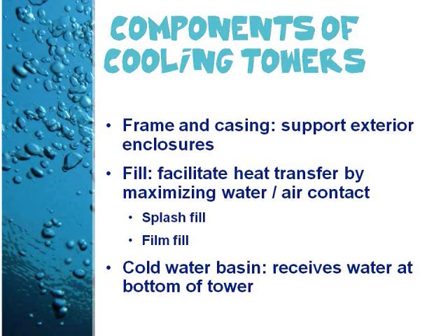The cold water basin is located at the bottom of the tower. It receives the cooled water that flows down through the tower fill. The basin usually has a sump or low point for the cold water discharge connection. In many tower designs, the cold water basin is beneath the entire fill. In some forced draft counterflow designs, however, the water at the bottom of the fill is channeled to a perimeter trough that functions as a cold water basin.